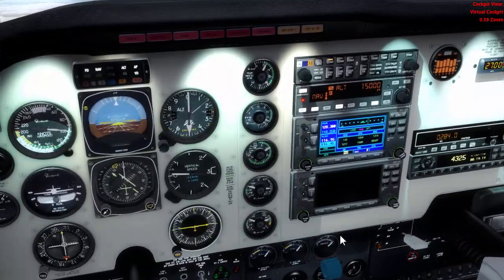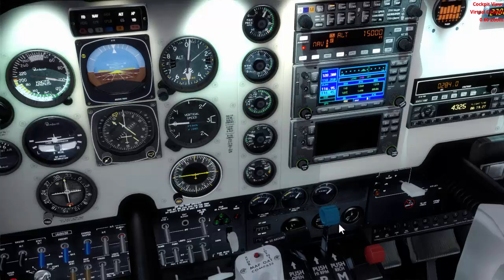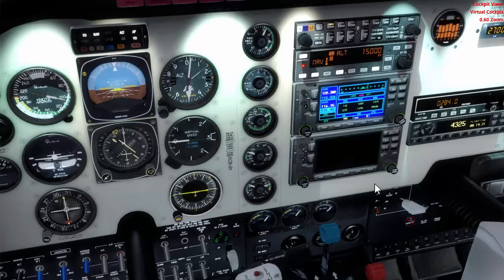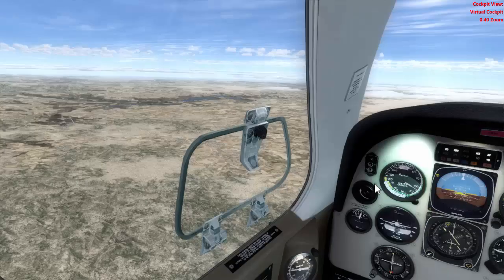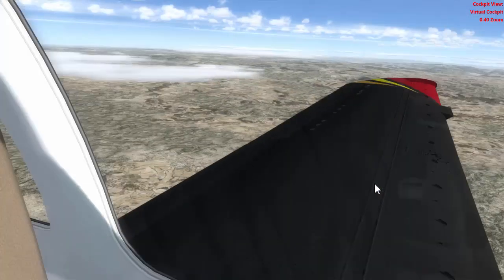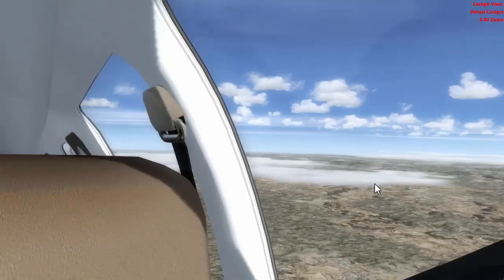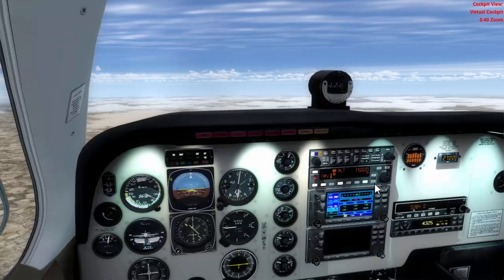In this case, because we are flying in GPS mode, we are following our flight plan and not a radial, because to reach a radial we need to fly in VLOC mode, and of course to have the VOR station properly tuned in the radio, in the navigation 1 radio. Okay, that is very important. So we have the sight there, and we are not very far away from Ibiza.